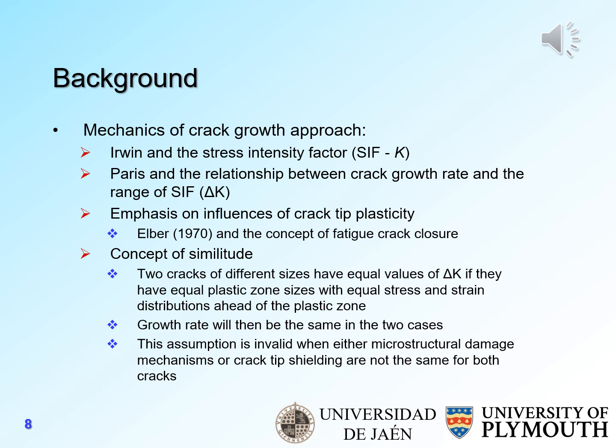And the idea here is, as you know, that two cracks of different sizes will have equal values of stress intensity range if they have equal plastic zone sizes with equal stress and strain distributions ahead of the plastic zone, and the growth rate will then be the same in the two cases. However, that assumption is invalid when either microstructural damage mechanisms or crack tip shielding are not the same in both cases.